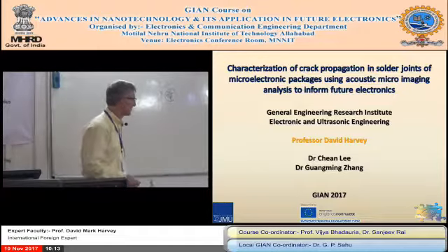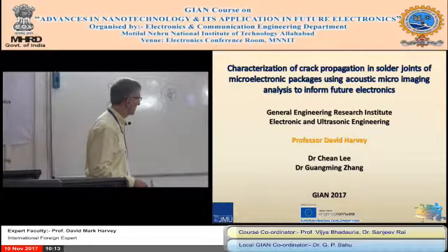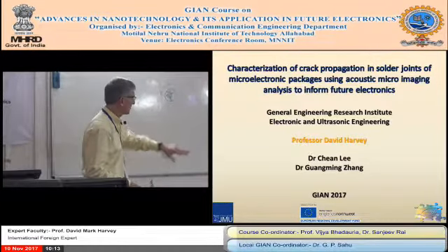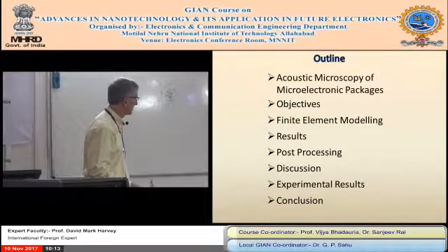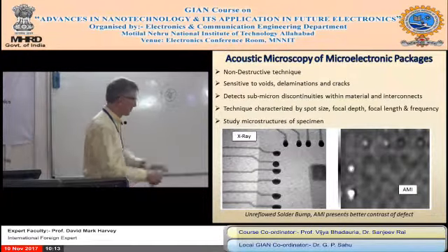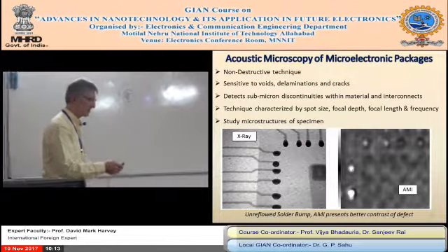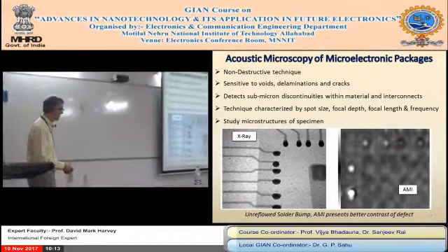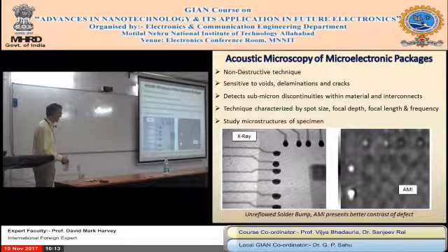So here's a couple of joints. These are all taken in our lab. This is from our X-ray machine. These are solder joints here. This is from the acoustic microimaging machine. Unfortunately, we're not quite on the same scale. So in the X-ray machine, you're looking for solder balls that have reflowed and there should be a certain shape. X-ray, you can see, it's quite detailed. This is sort of 1 micron resolution. You can see these, that one in particular, is slightly different shape to some of these. Look a bit more like the head on an old-fashioned match. So there's some faults there. And there you can see the bright points. This is where the joints have cracked or nearly cracked. So these should be more or less the same.